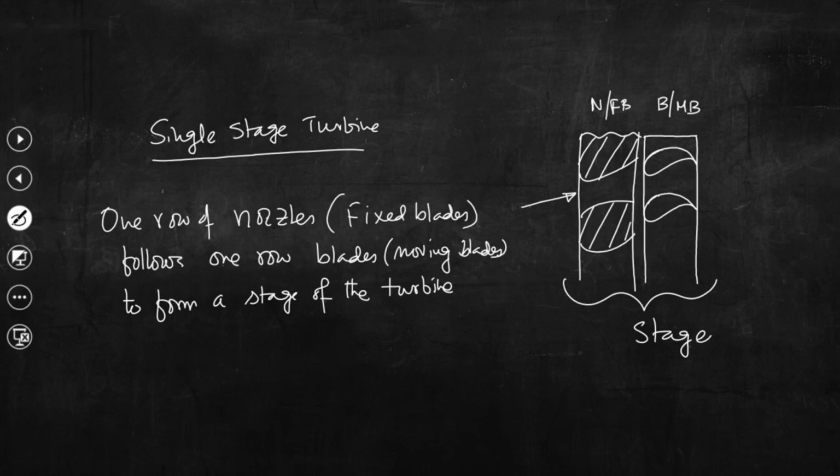That steam, while coming out, jets strike the turbine blades, and after striking, steam comes out from the first row of moving blades. Because of this blade angle, the jets suffer a loss of momentum, and that momentum is absorbed by the wheel of the turbine and it produces torque. So, if you would like to have the total pressure drop, that is the boiler pressure.